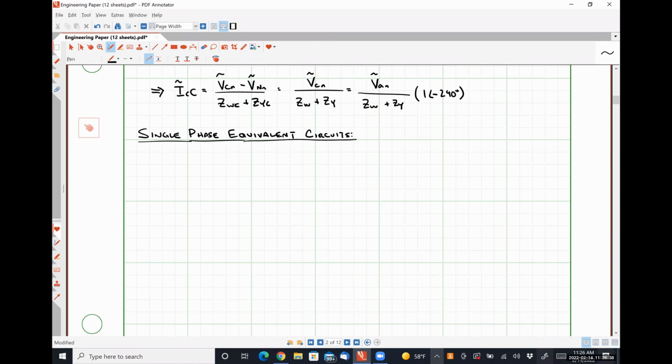Absolutely. Because the voltage drop over it is 0, and the current flowing through it is 0. I thought you were saying the current could flow through it. So the current flowing through the circuit will always be 0. So when I say an open circuit, I'm talking in terms of its impedance, an infinitely large impedance, right?